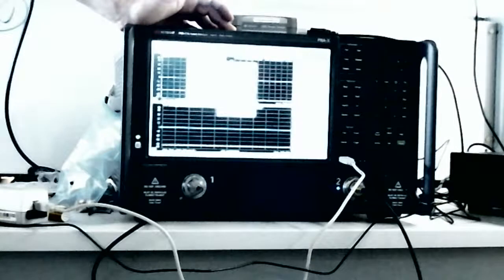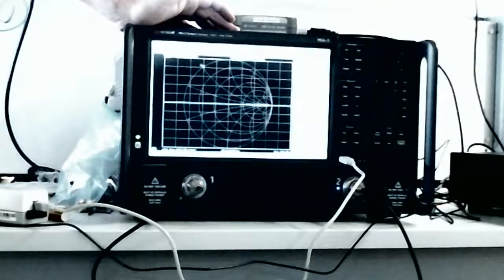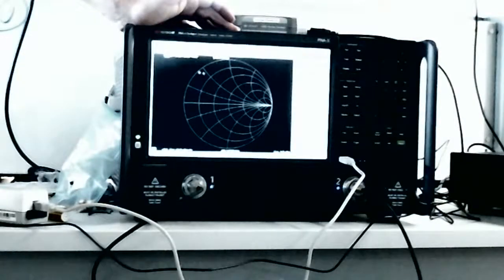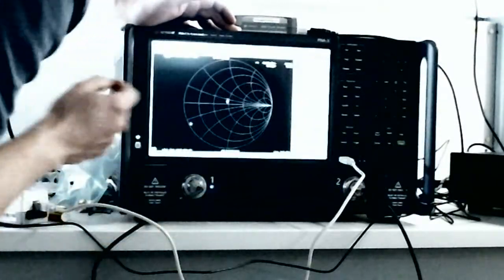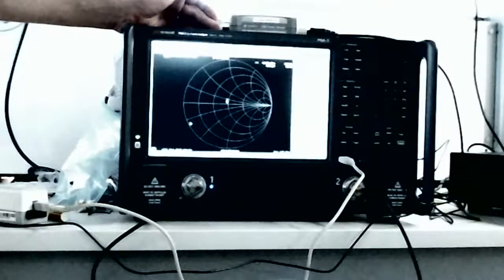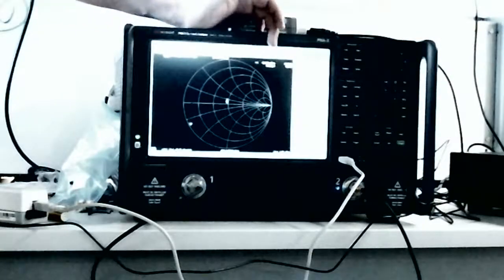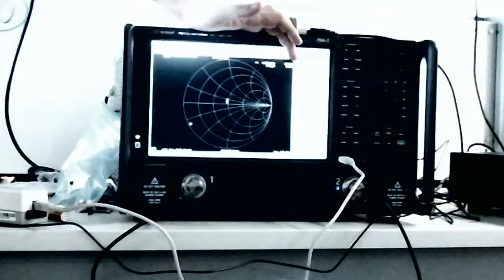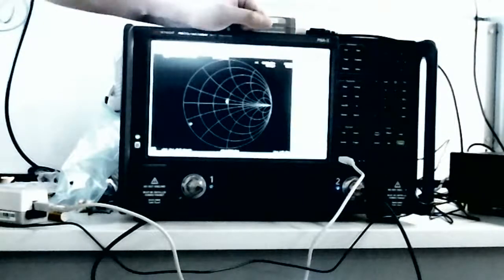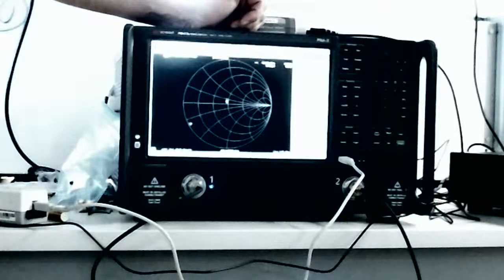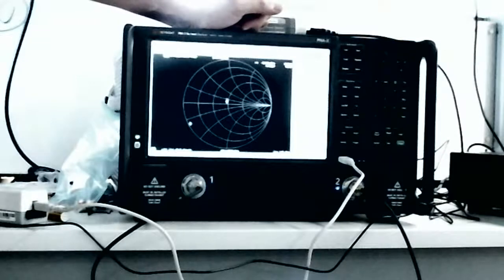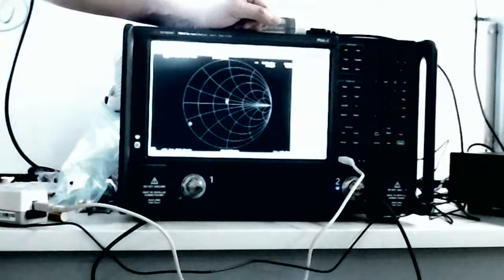And then if you're going to do matching, under format, you can access the Smith chart. And again, if I really want to, I can just ask where the Smith chart point for this is. If I put a marker on there, it's really small, but I can see here it's 47.38, 1.62, and that's the effective capacitance at that frequency. So this is a power sweep, that's why you're not really seeing it change, right? At one frequency, you're going to get a fixed return loss for this piece.